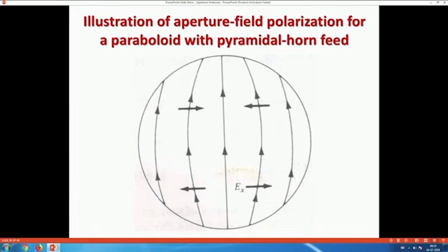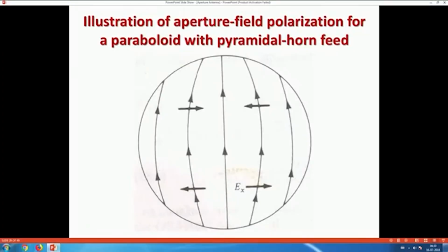Actually I have a large surface, and there we are assuming that we have a polarization like this, but because this is an aperture surface, there is no point in preventing cross polarized field. So, some cross polarized field will come because the horn is also giving that cross polarized component, then there are scatterings and various reflections on the feed, etc. All that gives this cross polarized field. That also needs to be taken into account, it can be estimated, but we are not going there.